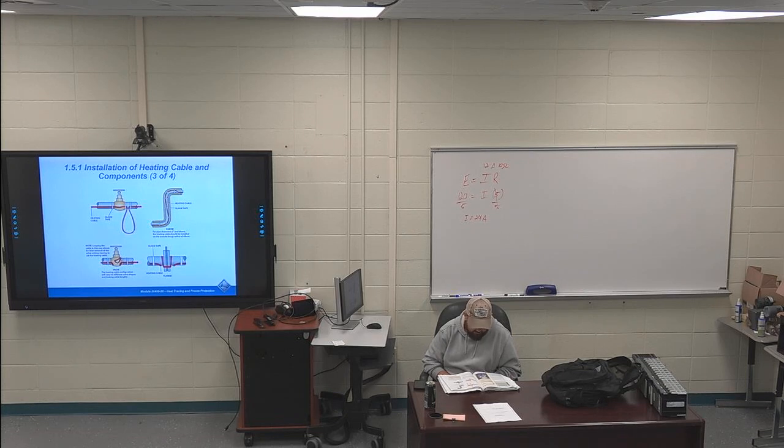On page 17, right after that highlight that you have in the second bullet point, the following considerations must be satisfied when installing sensors. So these are the actual sensors on the pipe itself. The third bullet point in the top right of 17 is highlighted. Sensors must be located 3 to 5 feet from any heat source or heat sink in the system. You don't want your sensors next to a heat source because it'll give a false reading of the entirety of the pipe. So you want it 3 to 5 feet away from any type of heat source.